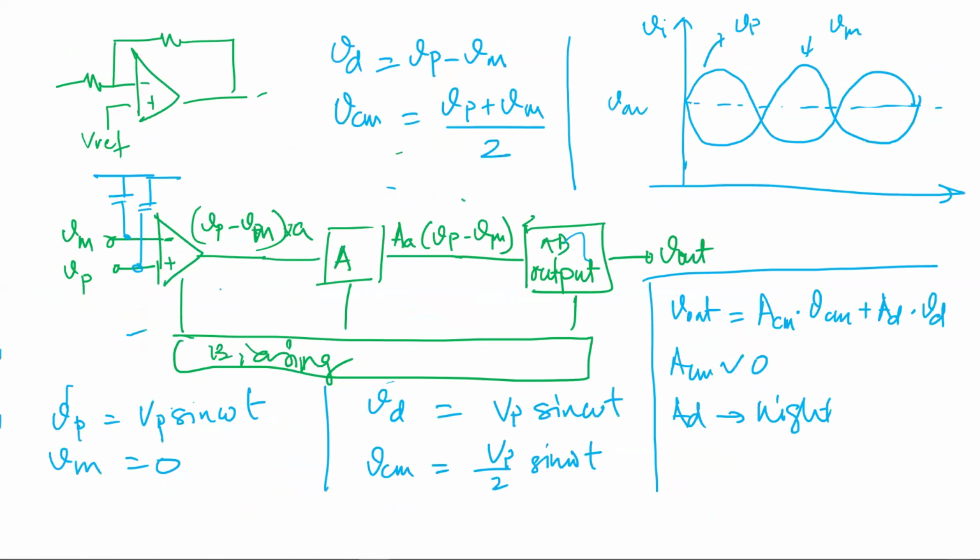So if you see in this architecture I was showing, first you created this differential to single-ended, then you created a voltage gain, and this output stage can be one of the output stages, but it's what's called a class A output stage, which means that it is always drawing current. So let's say you want to provide 10 milliamp to the load, then you always have to draw 10 milliamp in that branch, which will be wasting power.